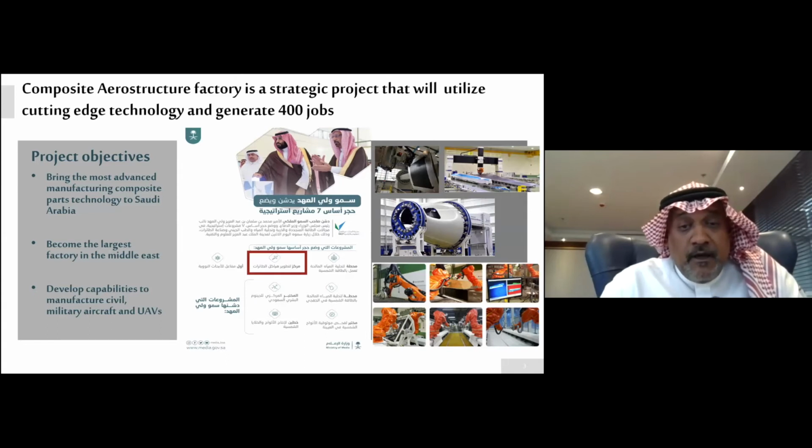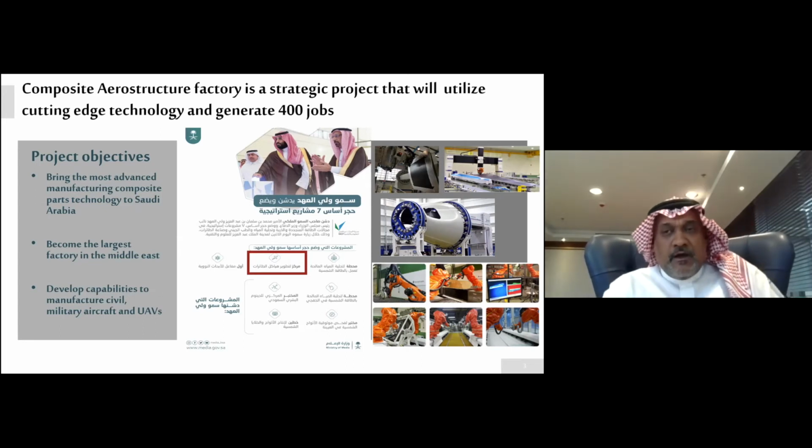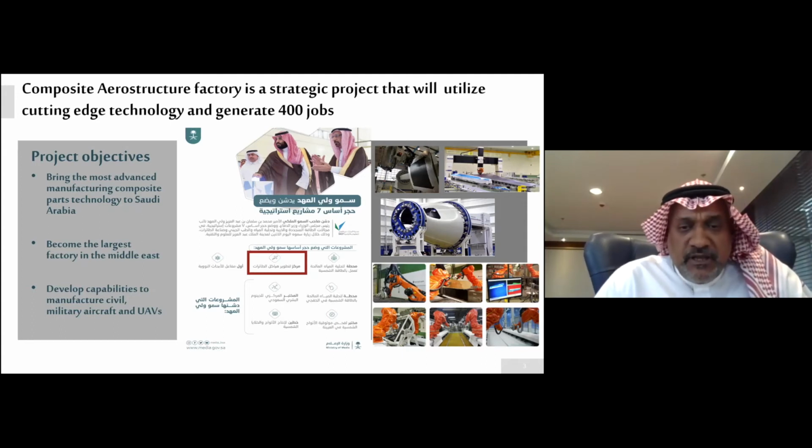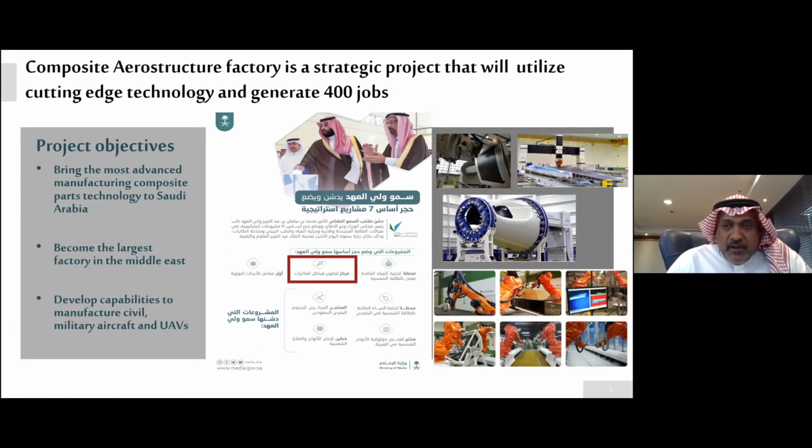It has all kinds of machines to make composite structure parts. I'll start with the first one. There's an AFP, automated fiber placement, 1/4 inch, 16 tows. This kind of machine is capable of making a section of fuselage. It's 9 meters in length, and it's utilizing unidirectional UD tape to make a section of fuselage, or any round or oval or even semi-square shapes.